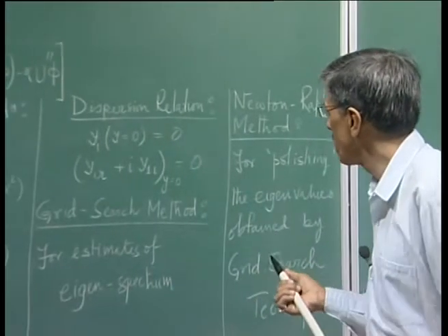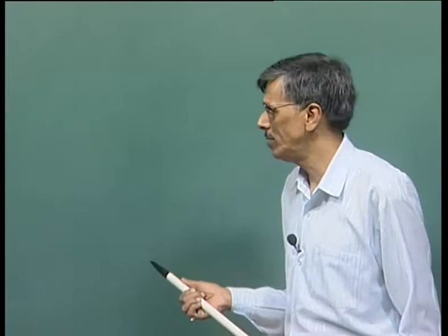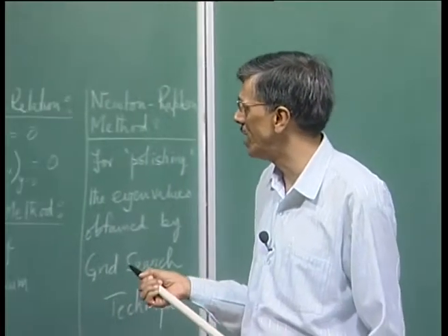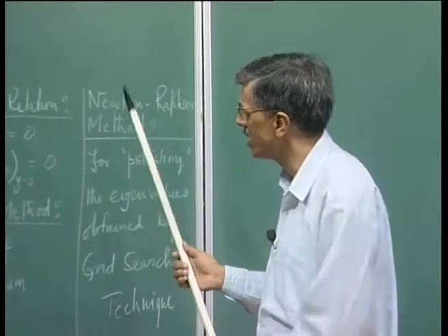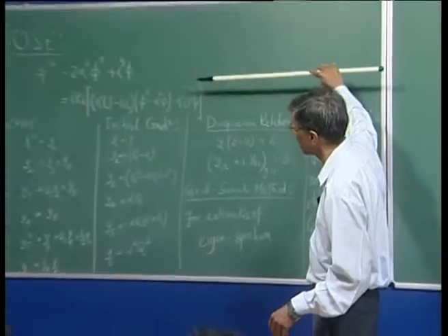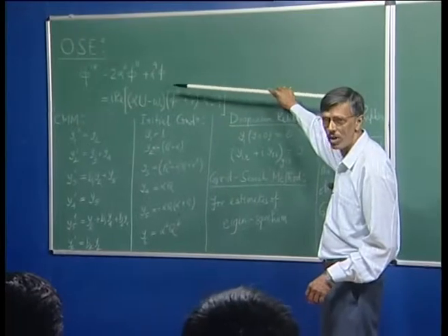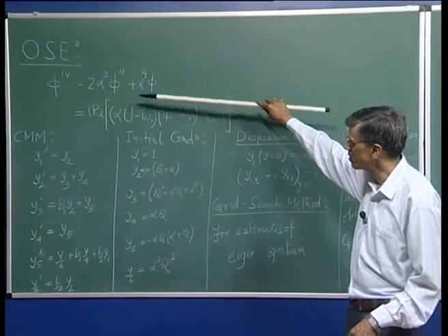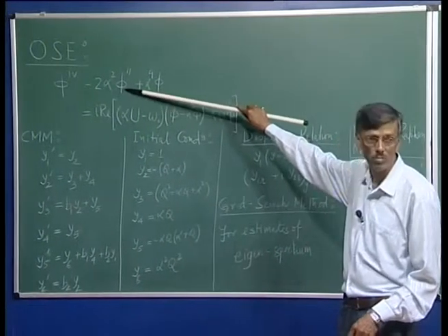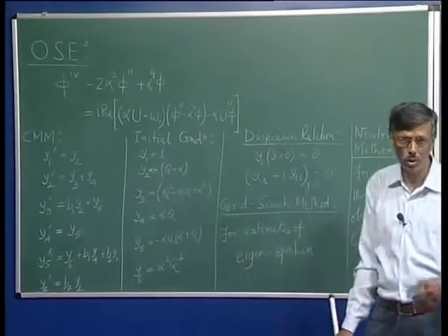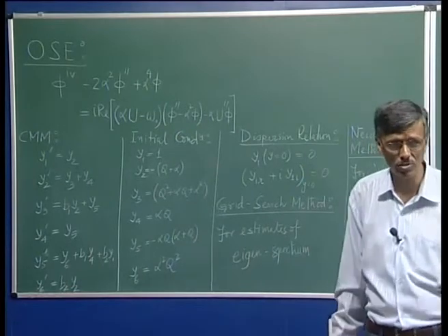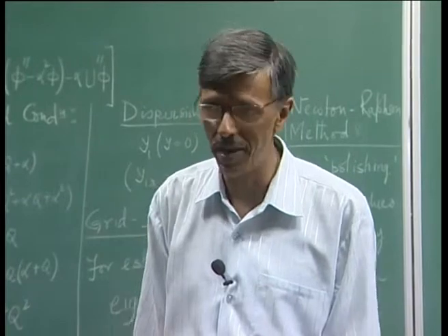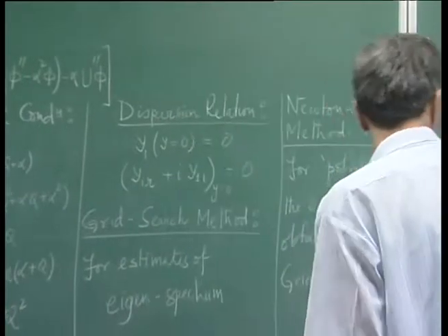Okay, let's now get back to the viscous instability study of a parallel boundary layer. Here, in a nutshell, we can follow the steps. This is our governing equation for the disturbance quantities, given in terms of the amplitude of the normal velocity. You also realize that normal velocity could also represent the amplitude of the stream function, because if I take a stream function like this,